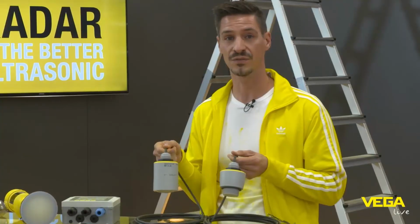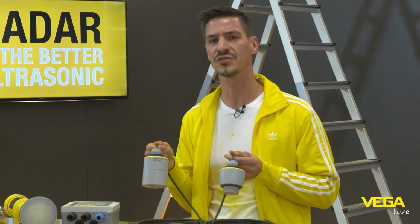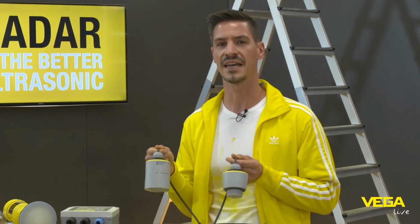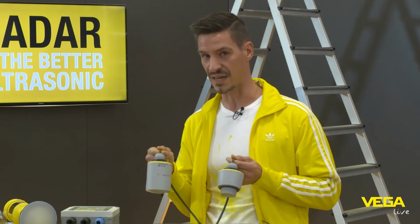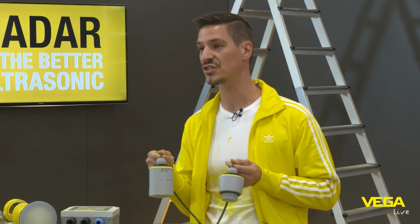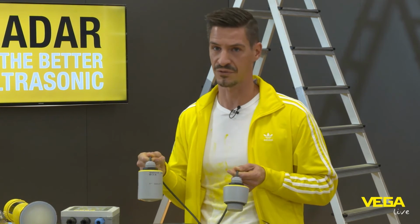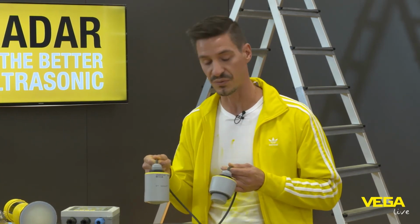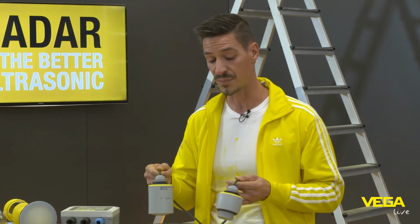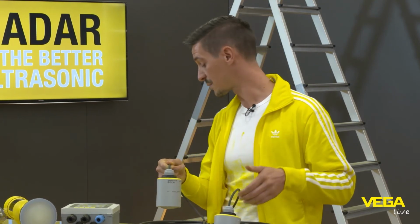It's our new radar devices, Vega Pulse Series C. From outside, it looks like an ultrasonic transducer, but inside is 80 gigahertz radar technology. That means now you can use all the advantages of radar within all the same applications like you had used the ultrasonic devices in the past. For example, small silos, containers, transportation silos, what have you. All simple applications where ultrasonic devices were used in the past, you can now use radar devices with all advantages. And the best is on exactly the same price level like you had to pay in the past for ultrasonic devices.